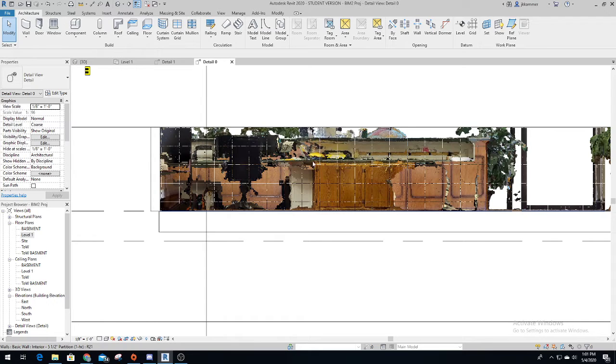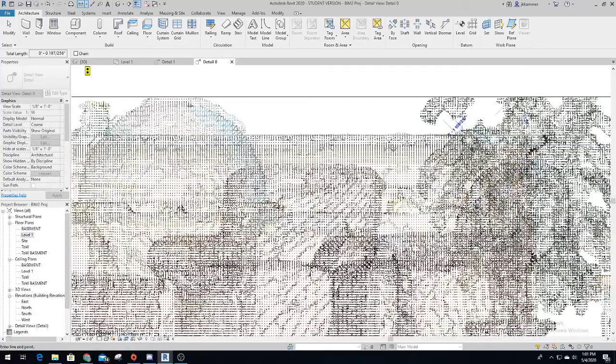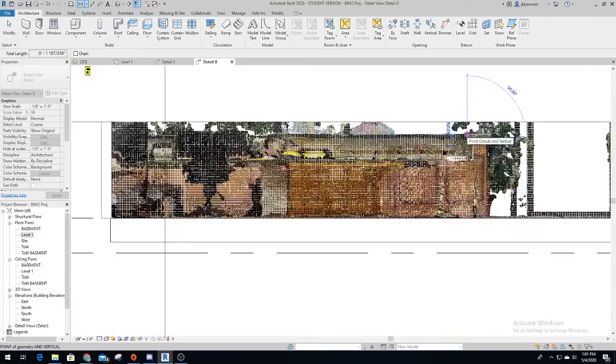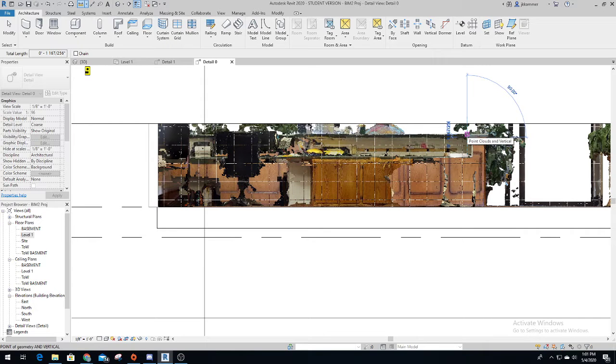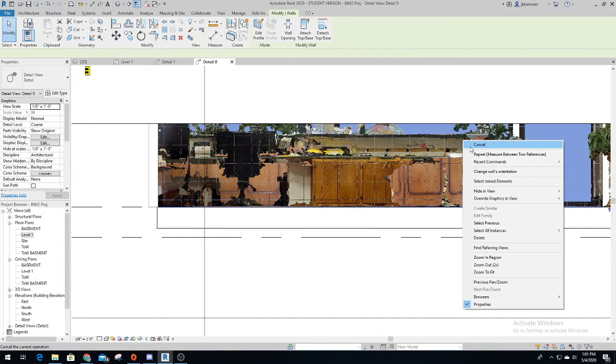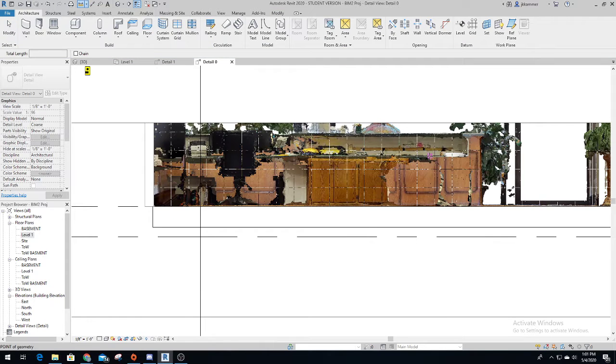Then we're going to have the actual tabletop, and then there's another section going up, and then another tabletop on the top. So measuring tool, that thickness of the table, let's just do it here because I can see it real nice here. Zoom in, point clouds, the more you zoom in, the grainier it gets. So it looks like just about 2 inches. I'm just going to call it 2 inches. Again, I can adjust it later. And then how tall is that back going up exactly? Again, let's just get a rough estimate here. Almost 12 inches, so let's just call it a foot.